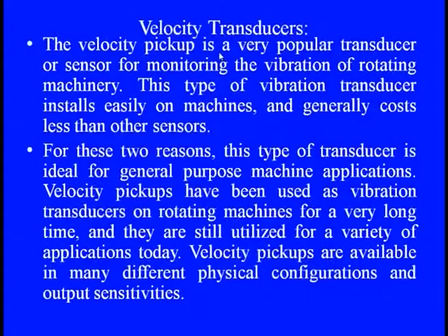The second part is velocity transducers. Velocity pickups are very popular transducers for monitoring the vibration of rotating machinery, because they can be installed directly on the machine easily, and they are very low cost compared to accelerometers.